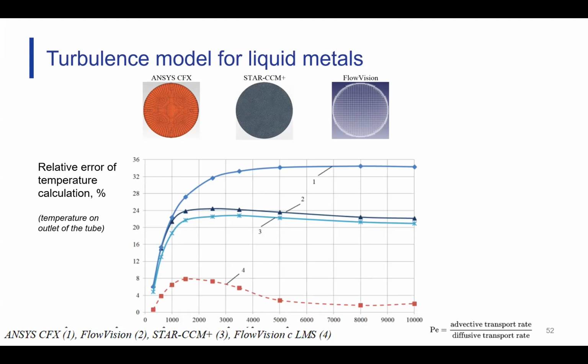But if we have liquid metals, however, this is going to be different. So the heat conduction becomes roughly of the same order for the entire flow. Therefore, the heat transfer mechanism is going to be very different, and so is the behavior of the flow. Therefore, we have special models that account for turbulent heat transfer by accounting for the turbulent Prandtl number. So this is basically the ratio of your flow momentum to the thermal diffusivity. And in nuclear applications, this isn't constant, this changes. So we account for that change with this model.